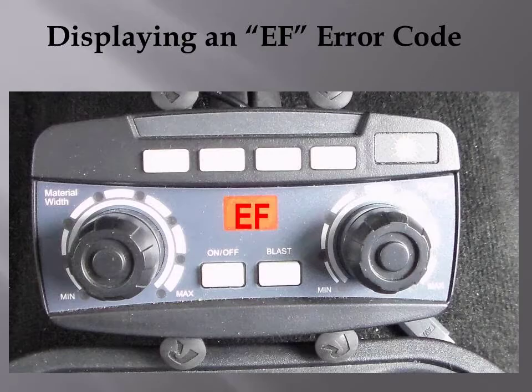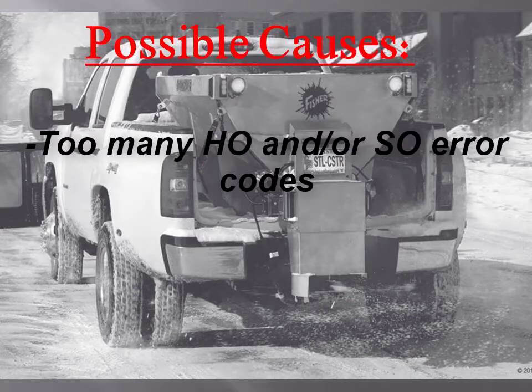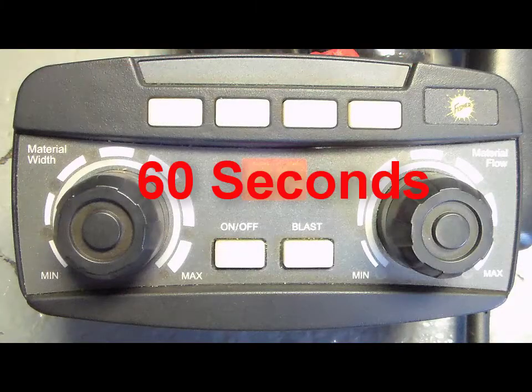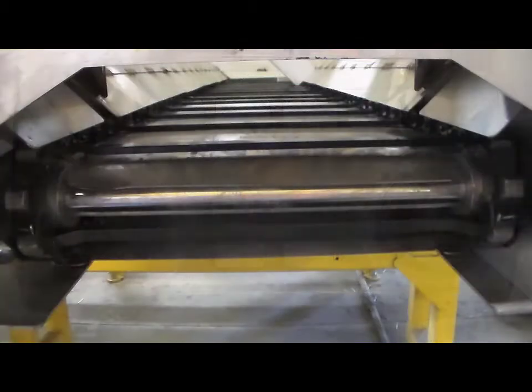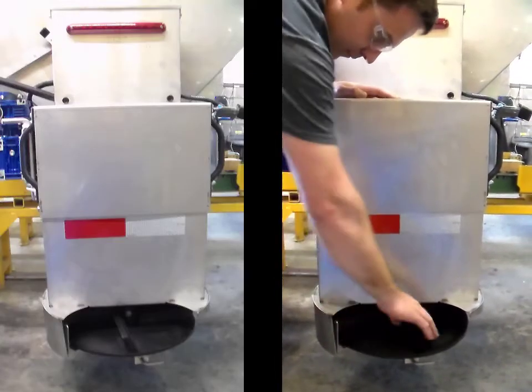When the EF code is displayed, this indicates that there are excessive drive faults. This could be caused by too many HO and/or SO error codes, as well as the hopper module overheating. The control will time out for 60 seconds to allow the module to cool. Ensure that the conveyor and spinner are not jammed and spin freely.